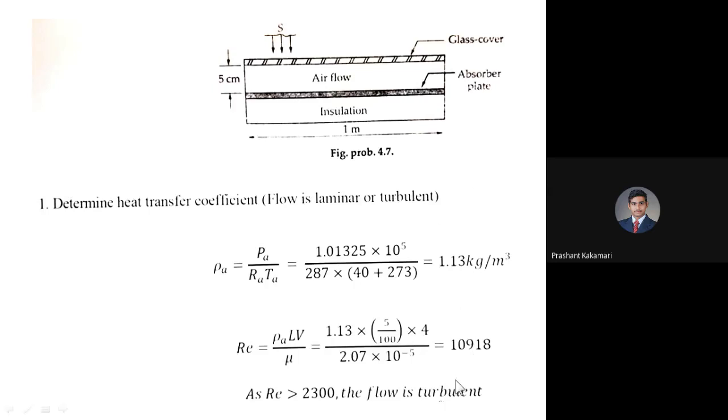Because laminar and turbulent flow are always differentiated by the values 2000 and 4000. From 2000 to 4000 it will be transitional flow. But exactly, if you see, it is around 2300. If you take 4000, after the transitional flow it will attain turbulent flow. So it is above the 4000 value. So I can tell this is a turbulent flow, not even in the transitional flows.